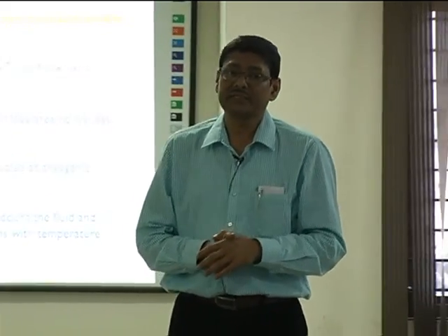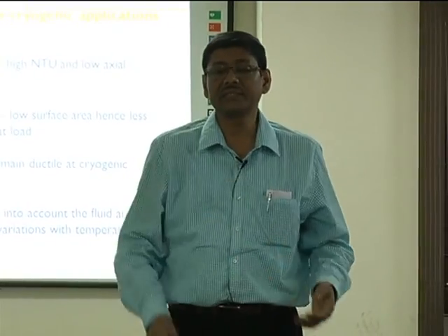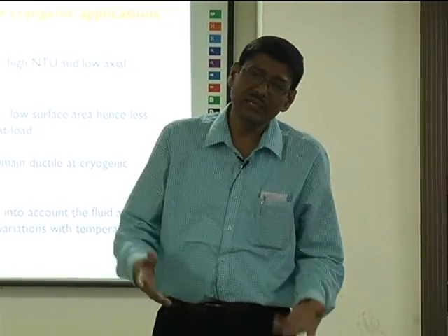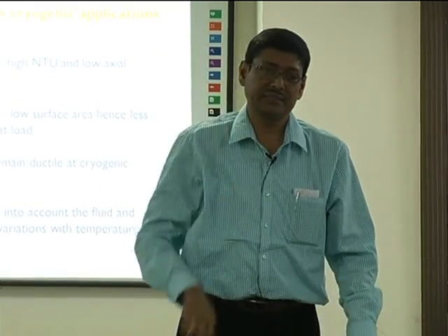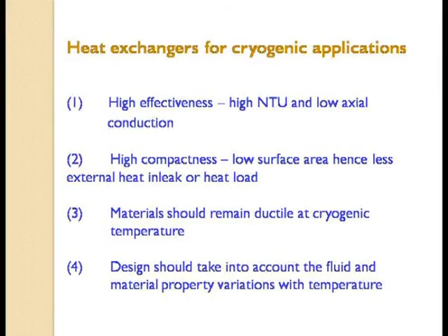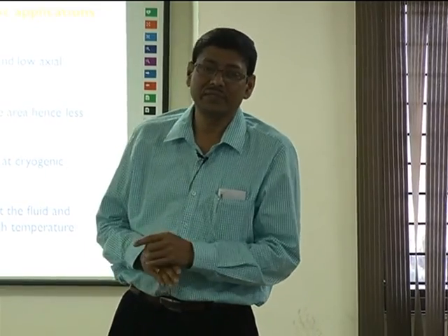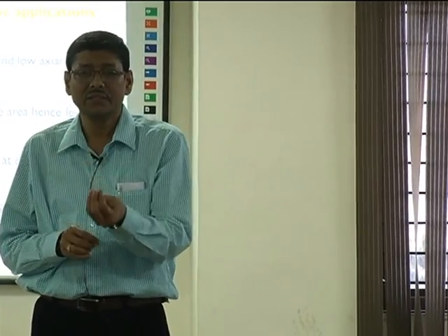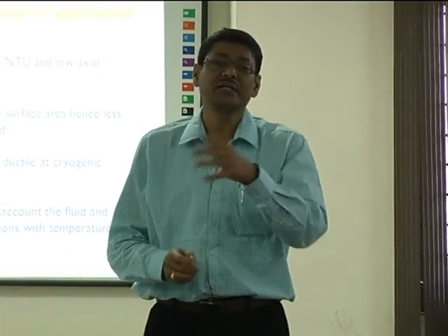But in cryogenic temperature, the cold fluid, as I said, has to be below minus 150 degrees centigrade. So definitely heat transfer in that region is different. One stream will be at extreme low temperature, the other stream will be at a slightly higher temperature, and you have to exchange the heat between those two fluids. Okay. Now suppose you have to liquefy air or nitrogen, you have a heat exchanger and then a Joule-Thomson valve, and after the expansion some temperature is reduced and the returned gas is used in a heat exchanger to recover the cold before it comes out of the heat exchanger.